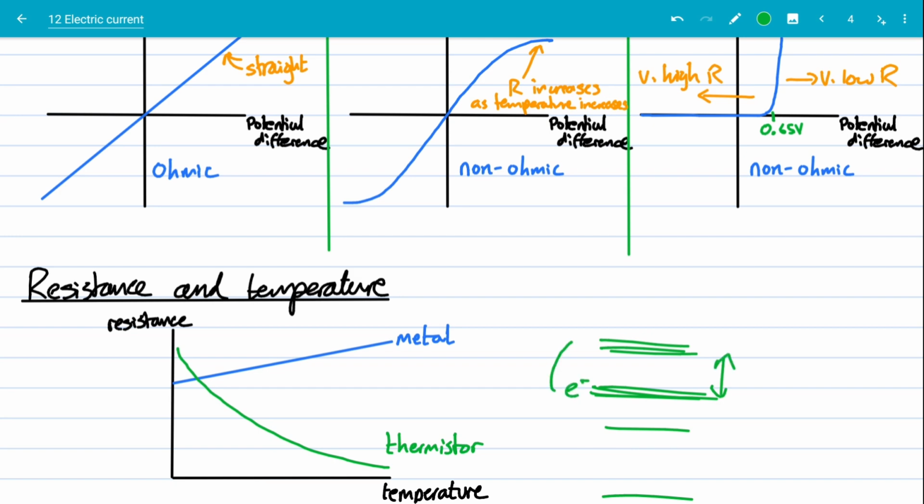And if you can get electrons to jump up over that band gap, then they're in a band which we call the conduction band. And in the conduction band, those electrons can move to the neighboring atom because there's no electron in it, and the atom next to that, and so on, and drift through the crystal lattice of this semiconductor with very, very little impedance.